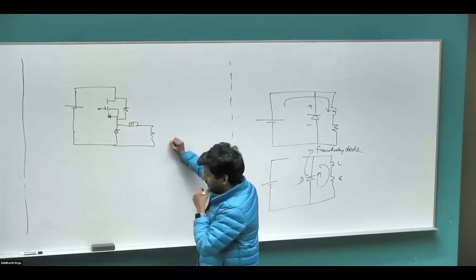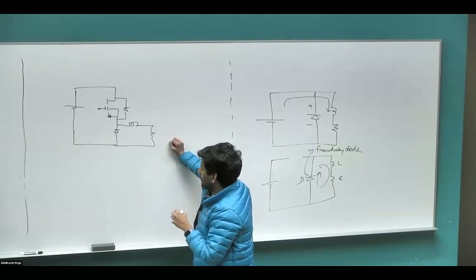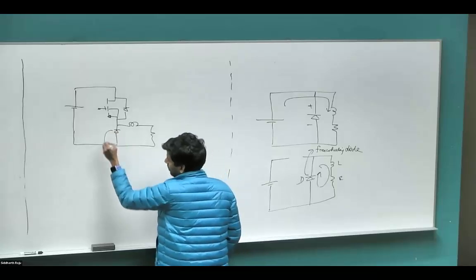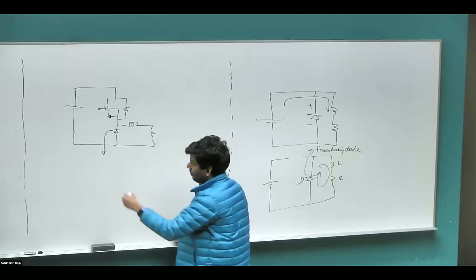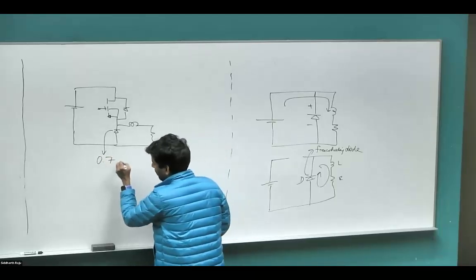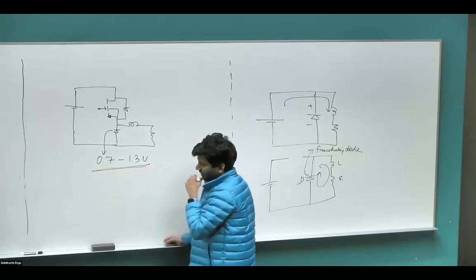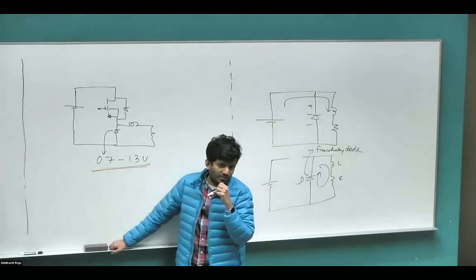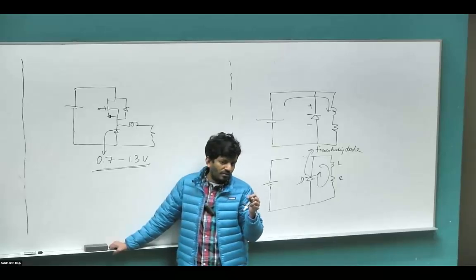So there's a bit of a problem with the structure that we have here. The thing is that the diode that is here drops quite a bit of voltage. In a power diode, that can be anywhere between 1.2 to 1.3 volts, which is a lot. Think of it like this: if you have a 100 ampere current flowing in this converter and you're dropping a volt across the diode, the power that's dropped in the diode is about 100 watts.